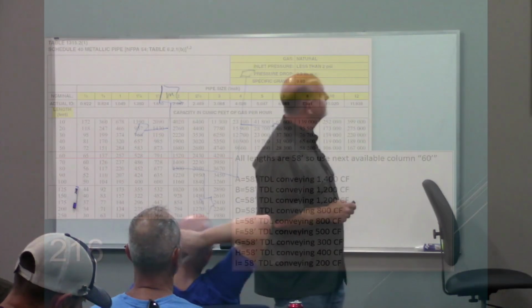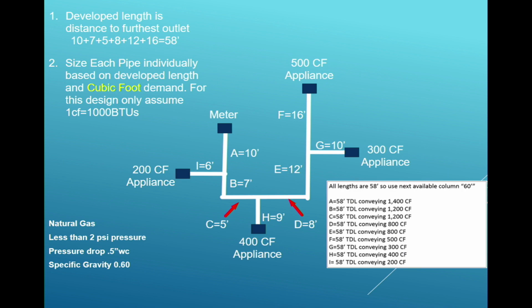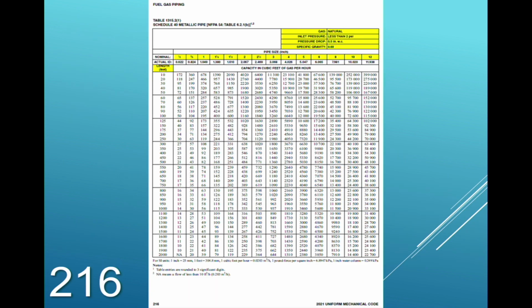Let's take a look at that. I've got the table cut off there. 1,400,000 at 60 feet, right? Do you agree I'd look at that and go, I don't even go that big, right? Now I'm lost. But again, notice that 60 feet all the way across, that's 151 or 152,000 cubic foot of gas, not BTUs. Okay? You guys okay with this? Yes, sir. Pretty straightforward stuff, isn't it?